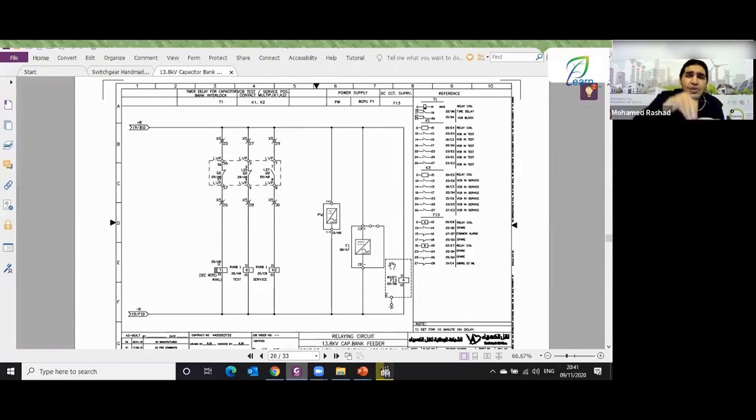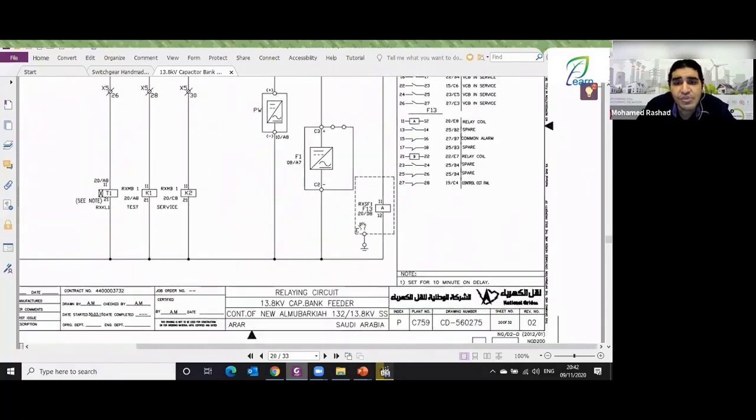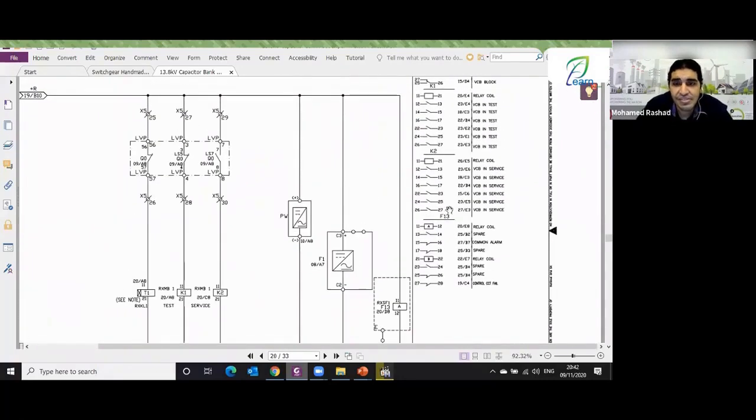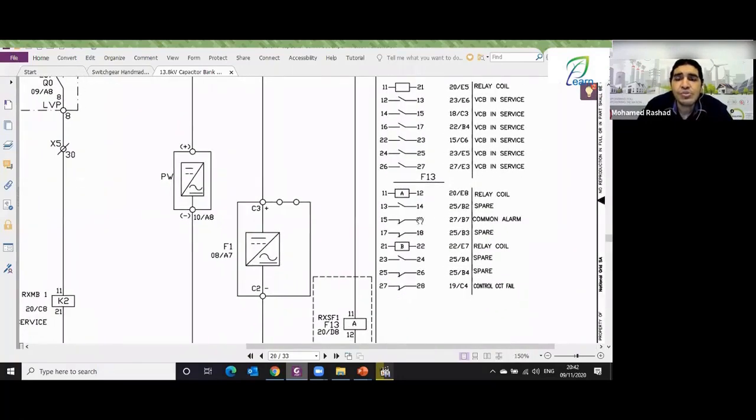This supervision is on the relay itself. Well, if the relay itself fails, it is supposed to trigger the alarm or connect it to the SCADA system. How do we supervise its circuit? If you look at this, which is mentioned on page 20, this is 8, which is F13, okay? You will find here there is something connected, going to something called common alarm on page 27,